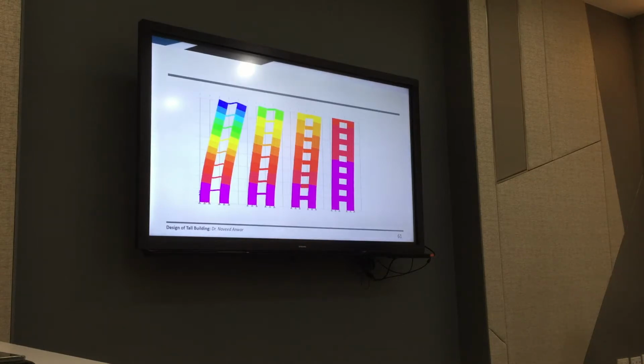You know that, right? You can bend something like this without breaking. It will only break when it breaks in shear. Bending does not cause failure. Shear does. See, I'm bending it. I can bend it that much. Can you imagine this deflection? This deflection is more than the length of the beam. I have no problem. So bending is not an issue. You can let something bend. So you can say this plastic beam is unbreakable because I was able to bend it so much, it didn't break. Of course, if I do it quickly, but that's going to be a local shear failure here. I'm going to break it.